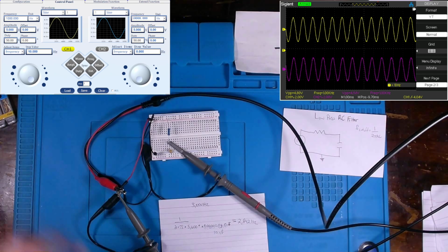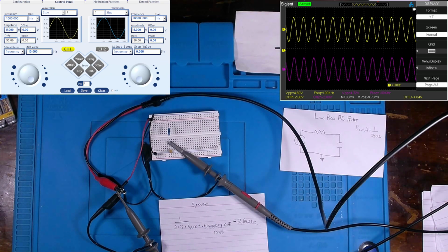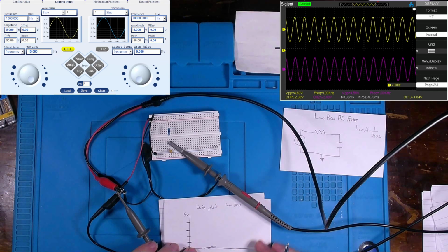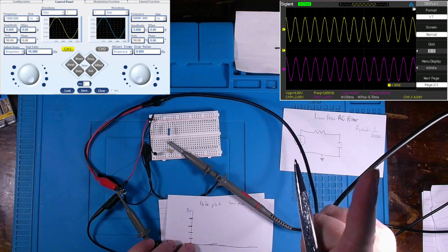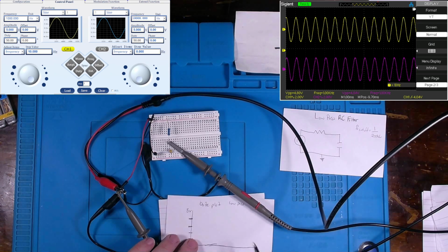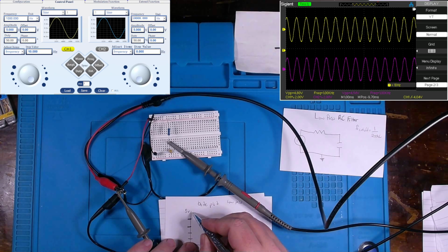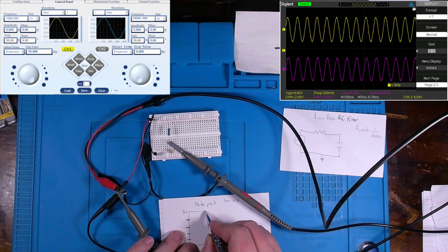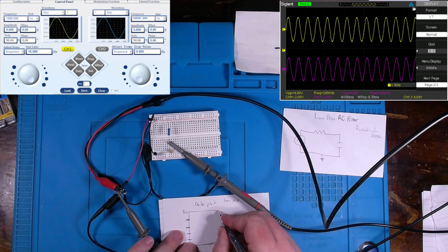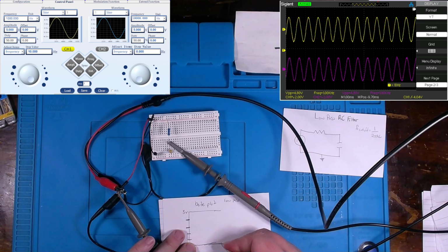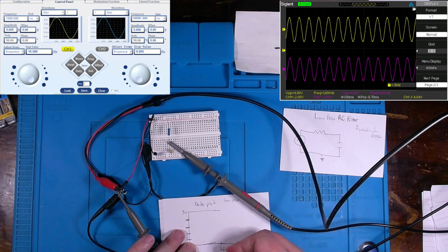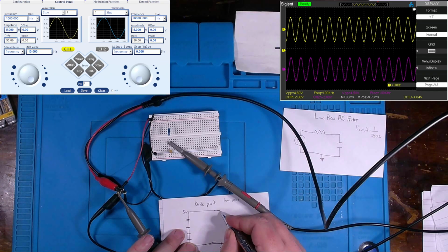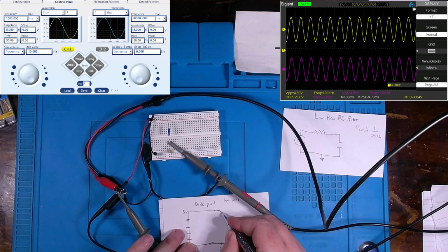Okay, but that is not what occurs. Typically in engineering, you establish something on a Bode plot. All right. And so what we're going to find out, and we'll verify this using our SIGGEN, is you're going to have something more akin to this, wherein your frequency comes through, right? And then once we're at that 2,842 hertz, we're going to see that it's going to start to drop just a smidge before it, all right?